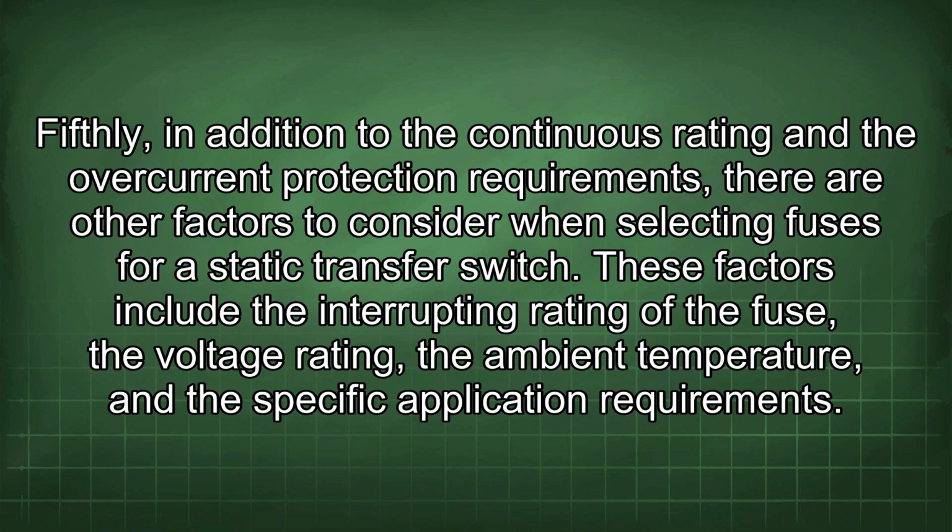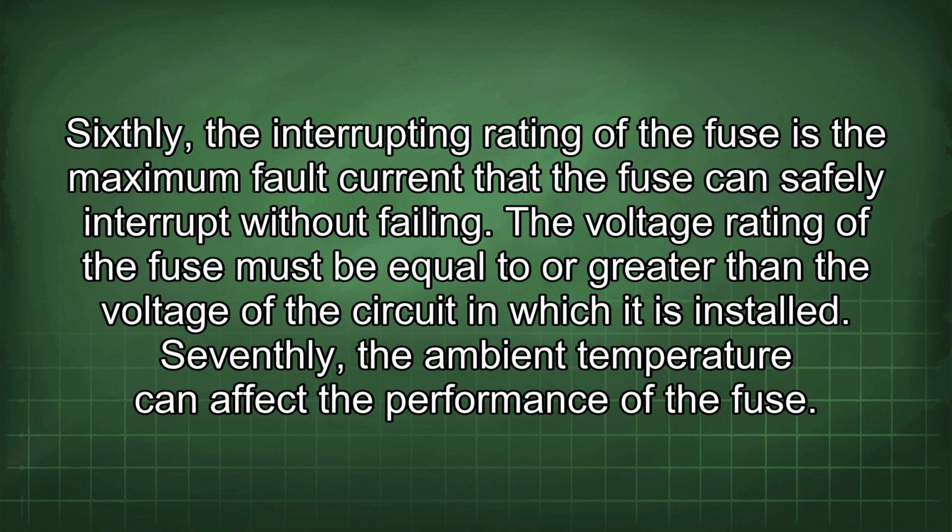Fifthly, in addition to the continuous rating and the overcurrent protection requirements, there are other factors to consider when selecting fuses for a static transfer switch. These factors include the interrupting rating of the fuse, the voltage rating, the ambient temperature, and the specific application requirements. Sixthly, the interrupting rating of the fuse is the maximum fault current that the fuse can safely interrupt without failing.